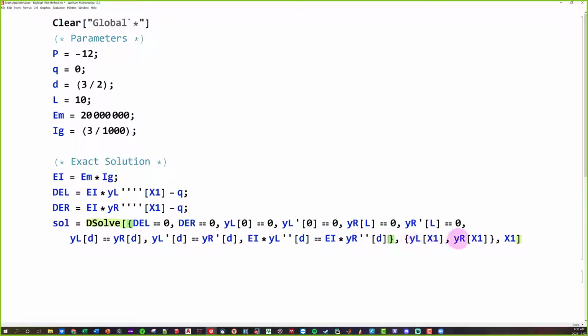I just want to let you know that. So he's saying, okay, we now have 7 boundary conditions. We only need 1 more. And if we were to look at location D, we've already covered displacement, rotation, and moment. And we know that there is actually a 4th internal force for us, which is shear.